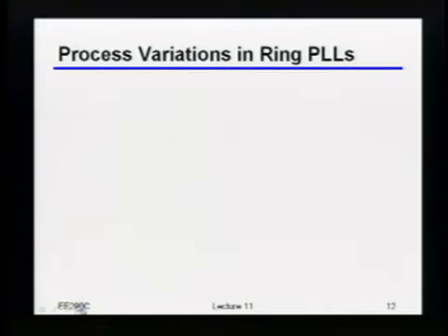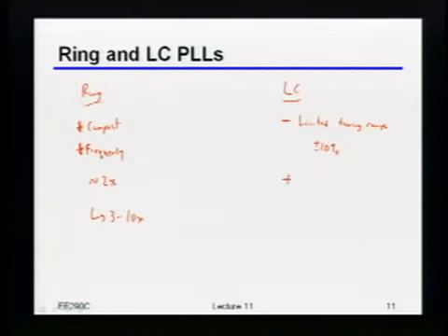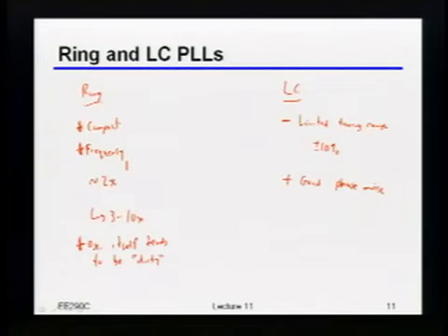Okay, so if I take that ring oscillator, and I should have put a 1 plus here, which is, of course, good phase noise. That's obviously kind of important. Well, the ring oscillator itself tends to be dirty, and the reason is that, since everything and its brother can move it around, it will.